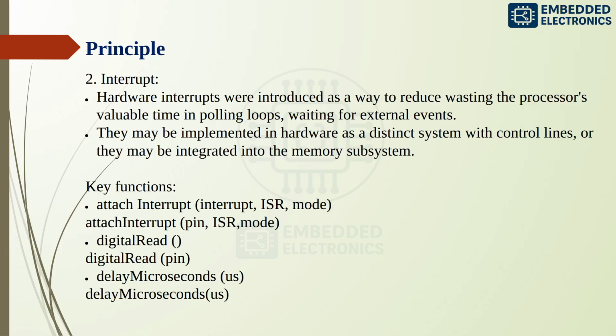Hardware interrupts are introduced as a way to reduce wasting the processor's valuable time in polling loops, waiting for external events. They may be implemented in hardware as a distinct system with control lines, or they may be integrated into the memory subsystem. So the key functions: one is attachInterrupt, with the pin, ISR, and mode.